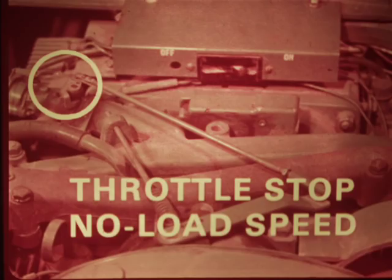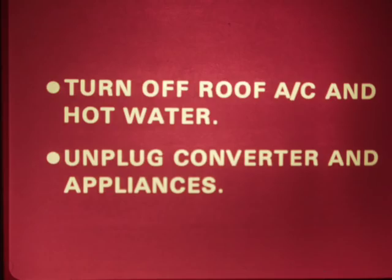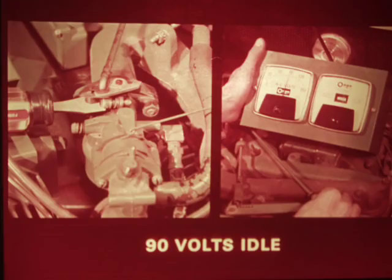To adjust the engine, first set the throttle stop screw and the no-load speed setting with 0 load on the generator. Leave the master breaker on so you can read the meter. Turn off the roof air conditioning and the hot water heater, and unplug the power converter and any other electrical appliances. Pull the governor arm rod all the way back so the throttle stop screw is against the throttle shaft lever, and hold the rod back. Set the stop screw for 90 volts at idle with the governor not regulating the speed.